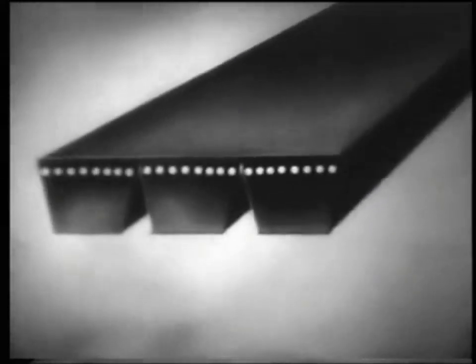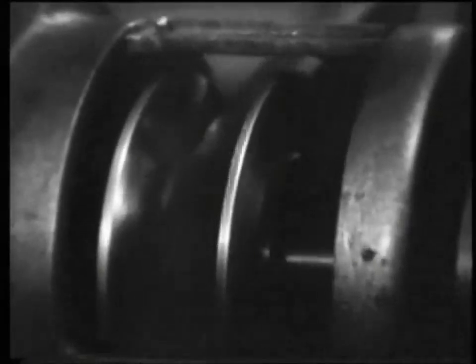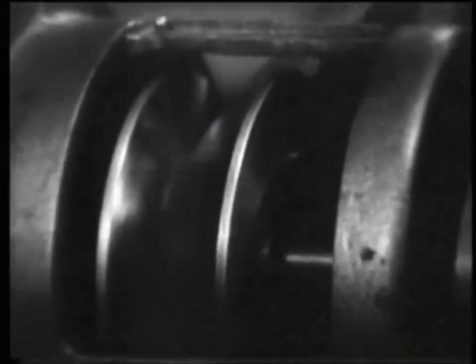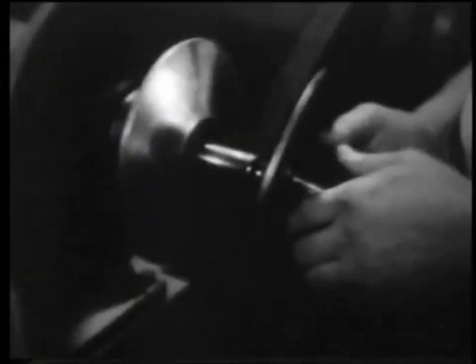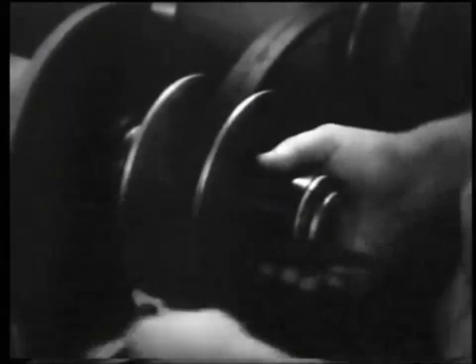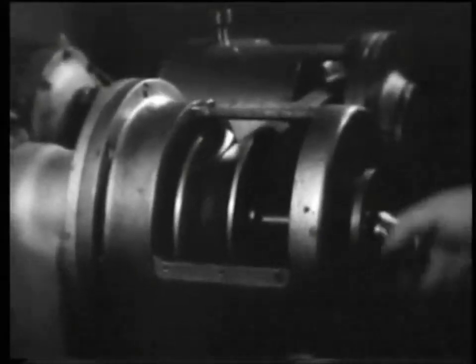Similarly to poly-V belts, multi-rib belts work, in which normal V-belts are united by a common base. Wedge belts are also successfully used in speed variators. The variator pulley consists of sliding discs forming a groove. The speed is adjusted by changing the gear ratios with the movement and sliding of the discs.